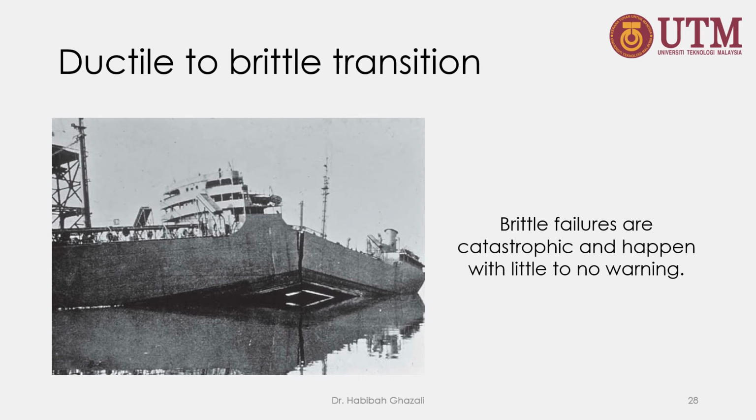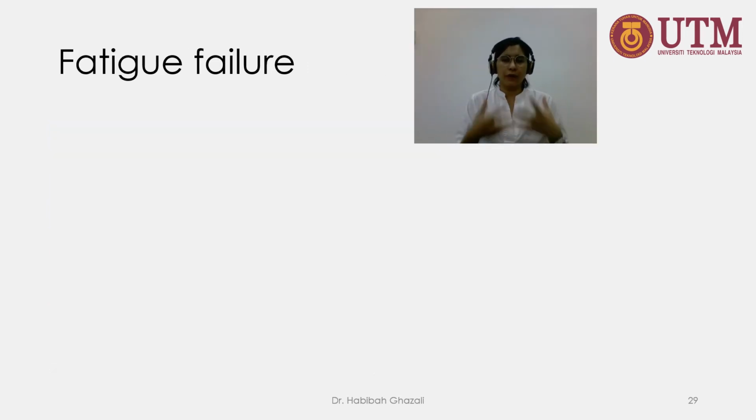To begin with, the steel that they use is a ductile steel. Materials can change their behavior when temperature changes, so you must be aware that this kind of failure can happen. With different types of materials, by doing impact testing, we can determine whether they are going to change their behavior depending on temperature.